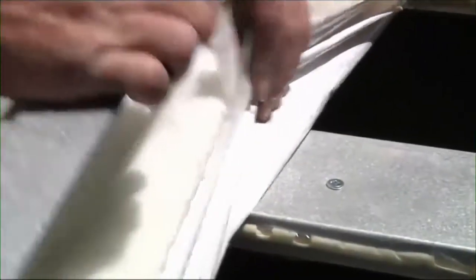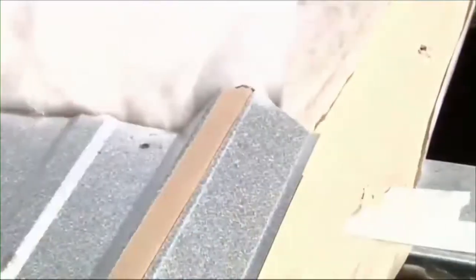The design of the fastener creates a stitch-type joint between the roof sheet and the thermal blocks, creating a watertight seal while fastening the whole assembly tightly to the purlin. The fastening process is very much like a typical screw-down roof. The only additional step is to set the thermal block in place with the 2 flathead screws and the use of the Sealed and Safe fasteners.